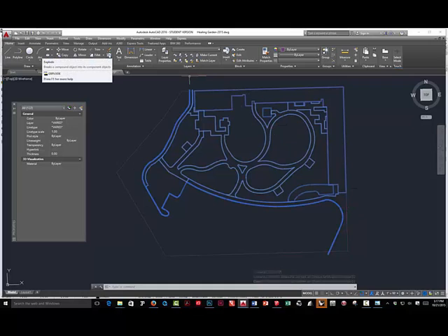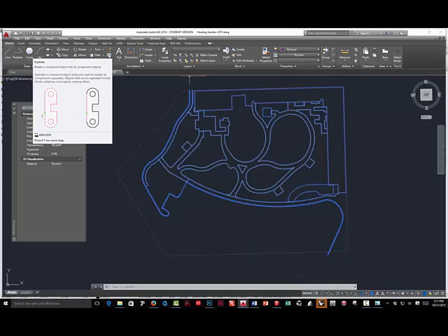Now the reason for this is you don't have to explode the lines. They actually get exploded when they come into SketchUp. The one entity that comes through, or two entities that come through into SketchUp from AutoCAD unharmed, are circles and arcs. So if you have a polyline that's straight, it always comes in as a series of segments, right? Because in SketchUp, it doesn't understand polylines. They're a series of connected lines. And for straight lines, that's good.